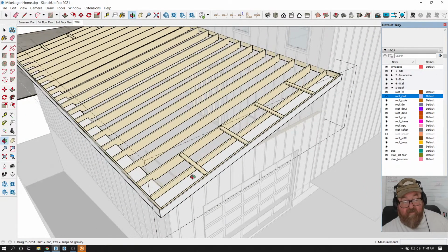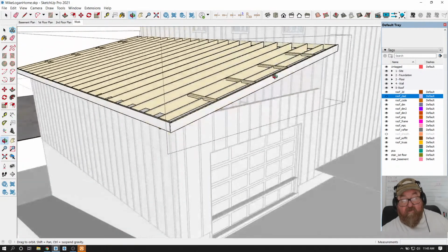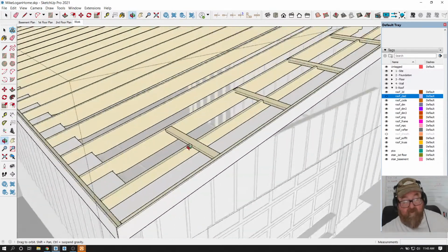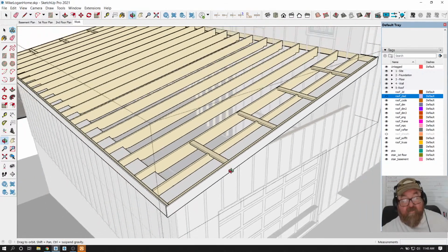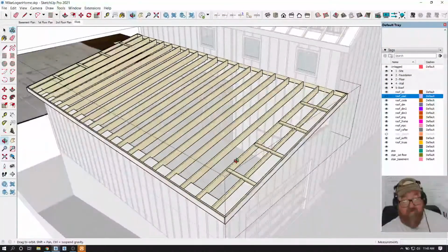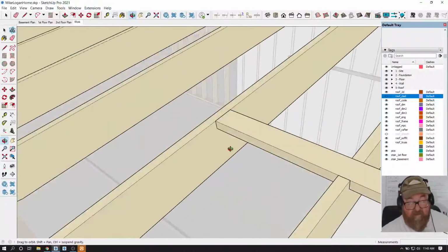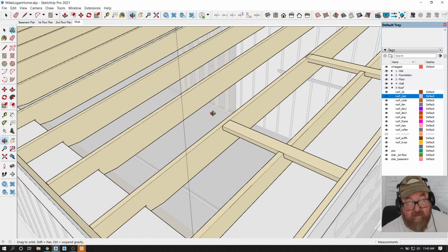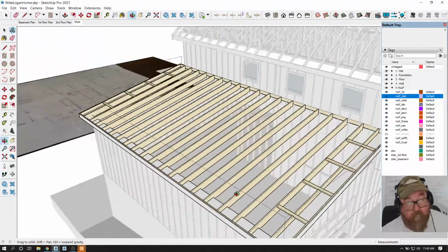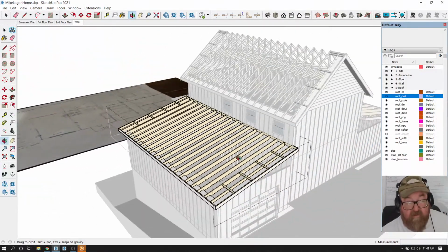It's a rafter above the wall, and so it's not carrying a load anymore. You don't have to worry about notching it out at that point, because you certainly wouldn't want to notch out a rafter. And that's why we don't notch this one. We just butt it into it, and the action of putting the decking on top of this keeps this from wanting to lean down. Kind of sandwiches it all.